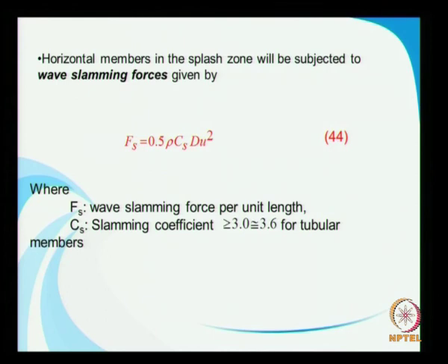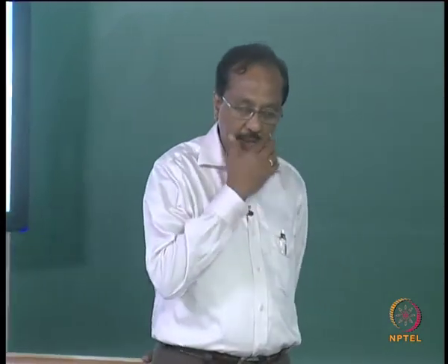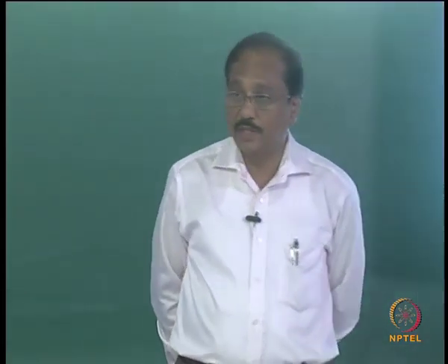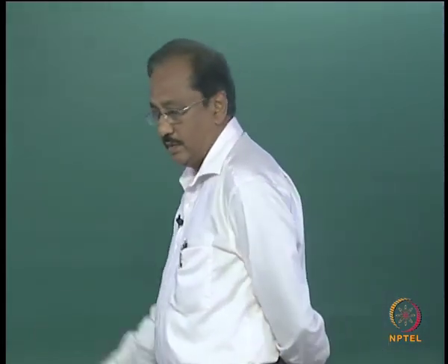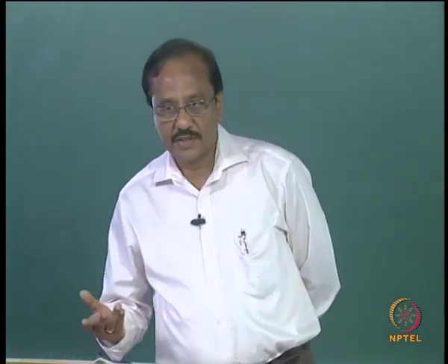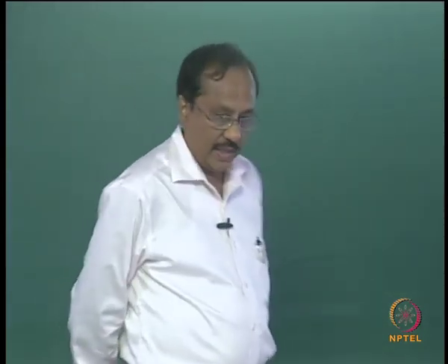With this we have covered forces on small bodies and large bodies, that is, in the diffraction regime. We have seen the linear diffraction theory, examined the Froude-Krylov forces, and now the slamming forces, and we have considered the most common types of structures, that is horizontal members, inclined members, as well as vertical members.